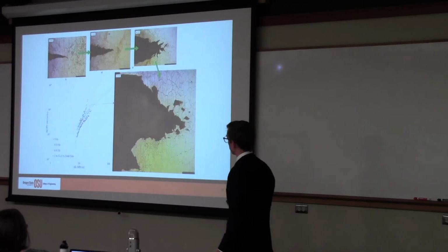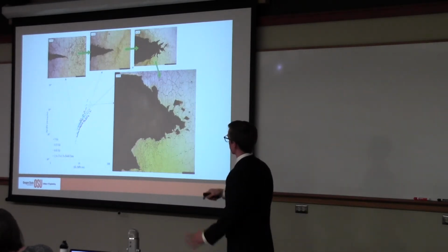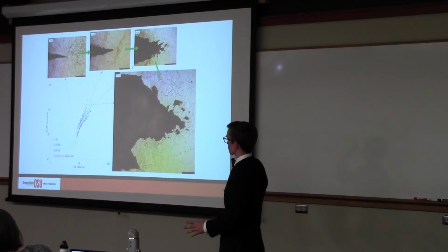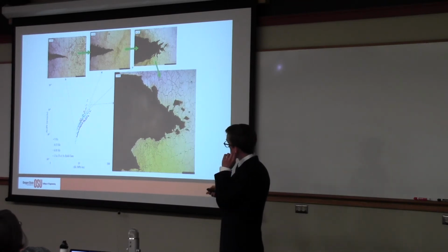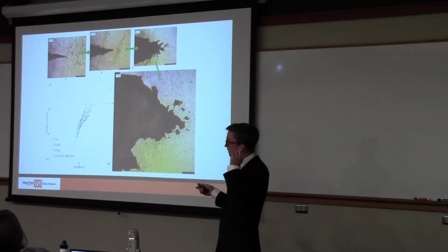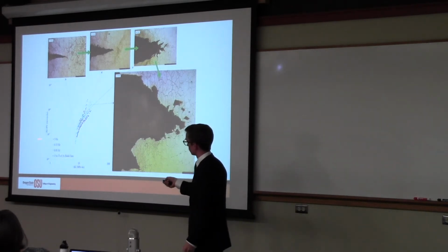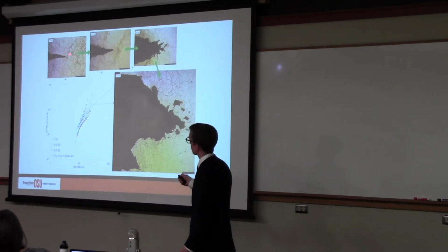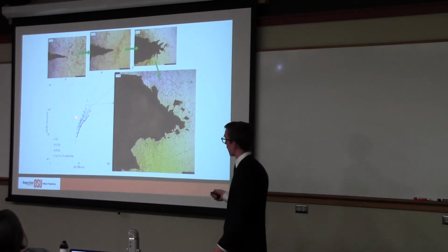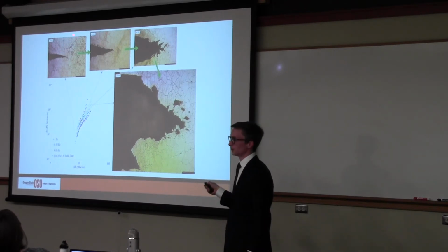Okay, so this might be the most explanatory of them all. These are etched micrographs under an optical microscope of 0.05 Hertz triangle wave samples, stopped at 4 different stress intensities on our classical plot, the very first plot that we looked at for fatigue crack growth per cycle versus delta K. And so the first one down here, it's going straight through the sample. It's transgranular crack growth. For a little bit higher stress intensity, you start to see these little excursions coming off. And maybe if you use your imagination, hey, is that a void forming? I don't know.